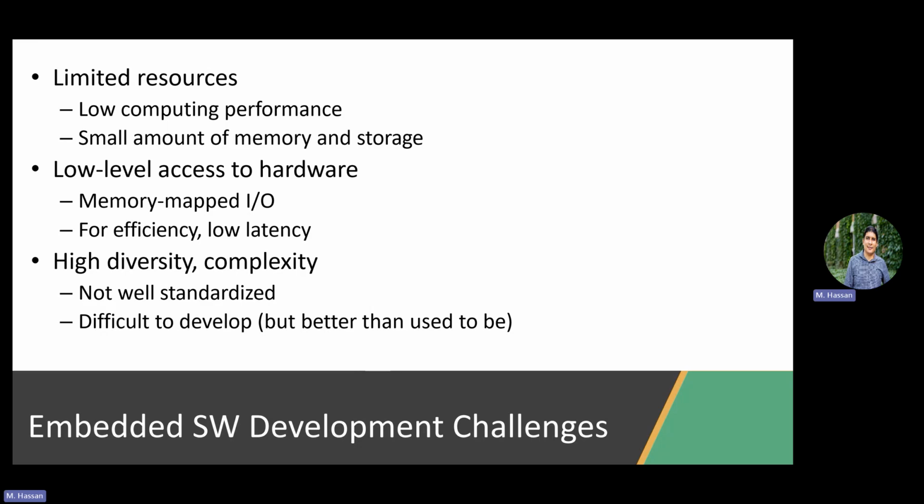The third thing is, compared to general purpose systems, where all the systems on a chip or processors more or less converge to a few options, either ARM for mobile application programming, or your laptops and desktops, which are mostly x86 machines, whether they are AMD or Intel. In embedded, there are so many companies, so many platforms, right? Last time we said ARM is the dominant one, that's true. But even ARM is not really a manufacturing company. They are a licensing company. They give companies the cores, and then the companies build the SoCs.